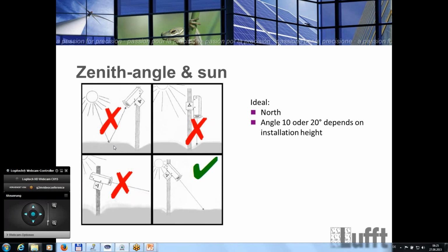Then you might have so much background light from the surface that the measurement of the sensor starts to produce errors when you have a direct reflection angle. This could happen. This is the reason why we suggest the fourth picture as a standard installation.